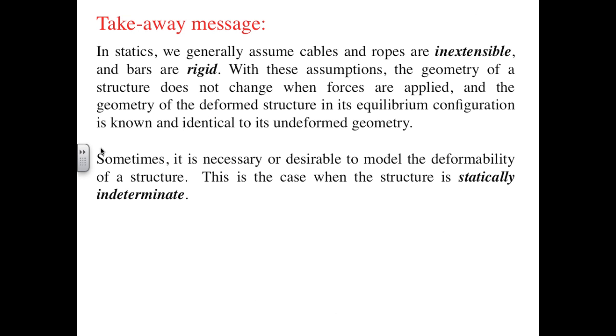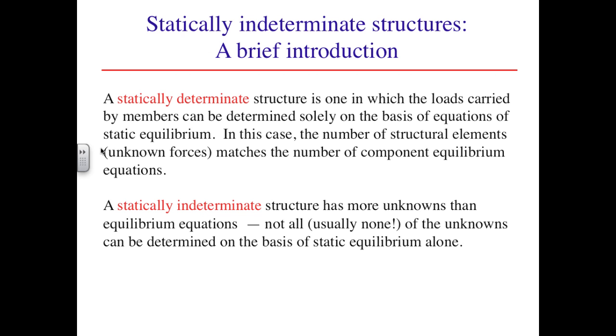This becomes useful in statically indeterminate problems where the movement of a joint from its undeformed to its deformed position implies a certain amount of stretch or contraction in members attached to the joint, which in turn tells us how much load those members are carrying. As a reminder, a statically determinate structure is one in which the loads carried by the members can be determined solely from the equations of static equilibrium.